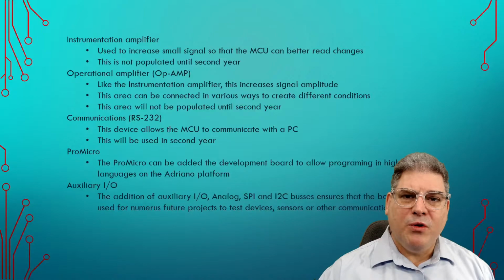So if you did want to remove the microchip processor and put the Pro Micro, all of these hardware ancillaries are available to you through the Pro Micro. So if you want to program in C++ and use the Arduino IDE, feel free. Okay, and do remember though that it is now at 3.3 volts, so you're going to want to make sure that you have the 3.3 volt Pro Micro.